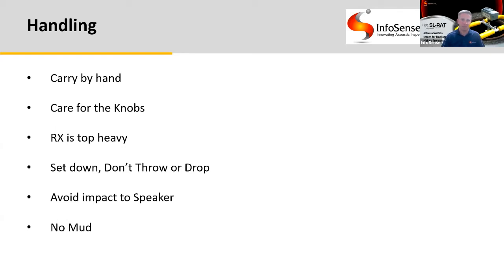The knobs that lock the pivoting arms in place should be used with care. Loosen the knobs to rotate the pivot arm and tighten it again once it's in position. There is a flat, recessed internal part in the pivot that can be damaged if the knob is not loosened before forcing the arm to rotate.